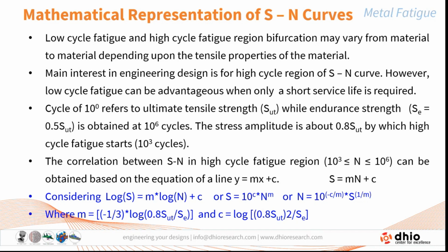That is, when the stresses are within the elastic limit, the high cycle fatigue starts. Thereby, the correlation between the stress and the number of cycles in the high cycle fatigue region, where the number of cycles is greater than 10 raised to the power of 3 and less than 10 raised to the power of 6, can be obtained, derived by mathematical equations which give the equation of a straight line, y is equal to mx plus c. Replacing y by the stress and x by the number of cycles, one can write this as S is equal to m into N plus c.